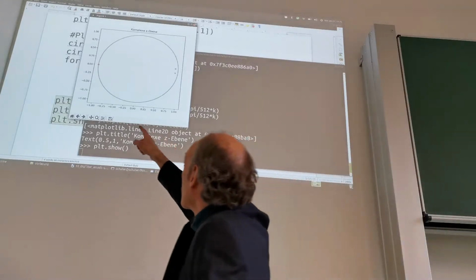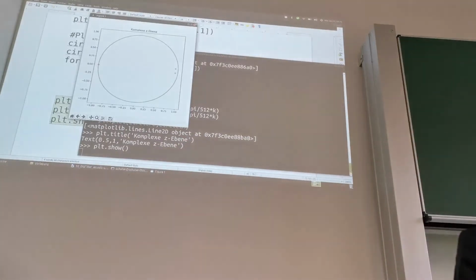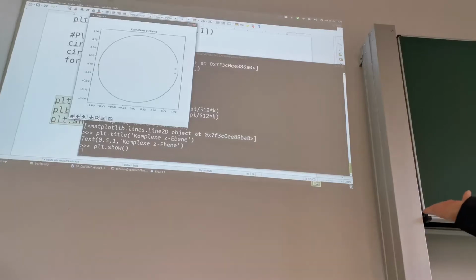And here you can see the two zeros at Nyquist at -1. So when you now go along the unit circle starting at angle 0, then first you come close to the poles. That means the output gets really large. Right? This is the pass band. And then when you continue to go with larger angles, then you come close to the 0 at Nyquist. That means the output is getting smaller and smaller until you have no output at pi, at angle pi.